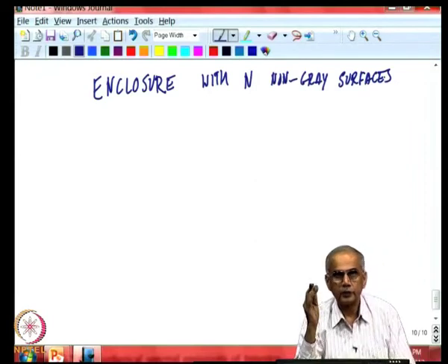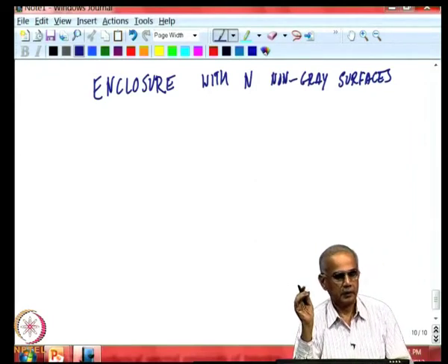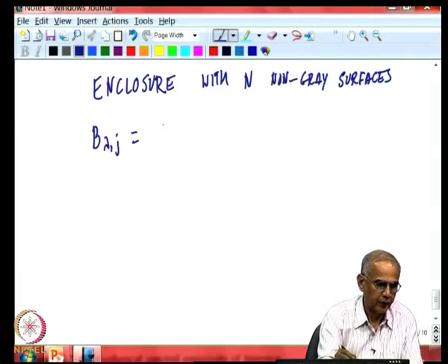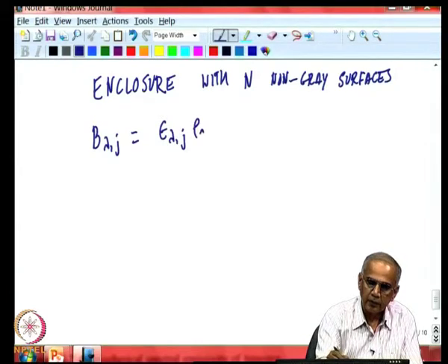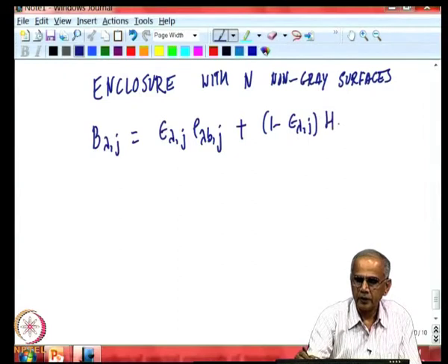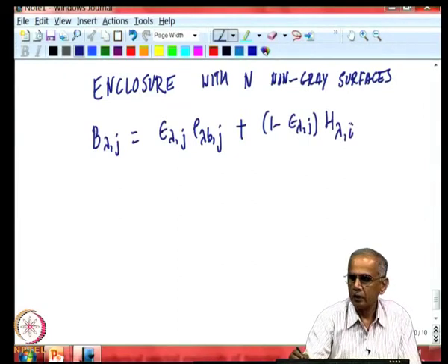So, if you have an enclosure with n non-gray surfaces, then for the jth surface the radiosity will be defined as the emissivity of the jth surface times the black body emission of the jth surface plus what is reflected of the irradiation on the jth surface.